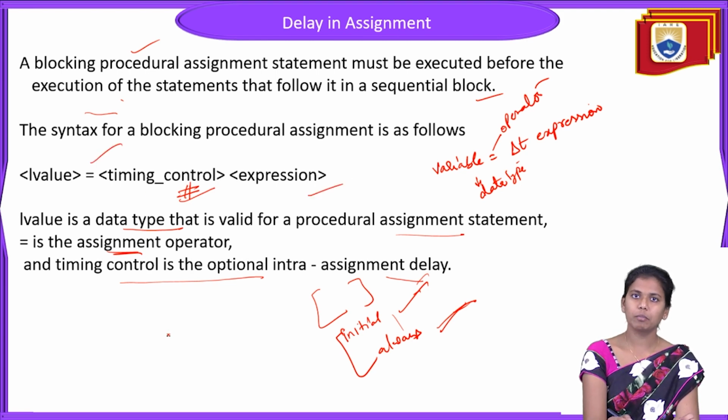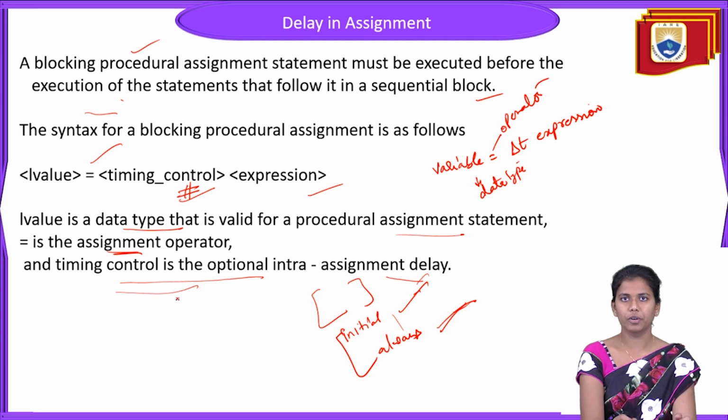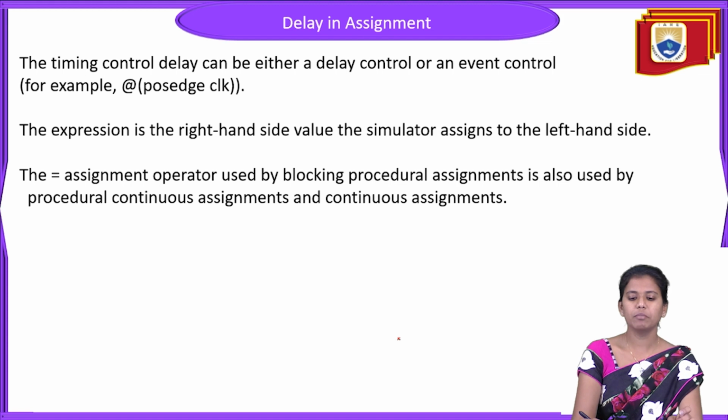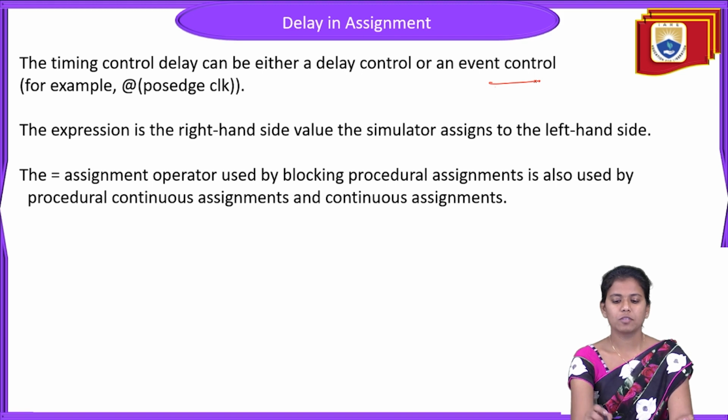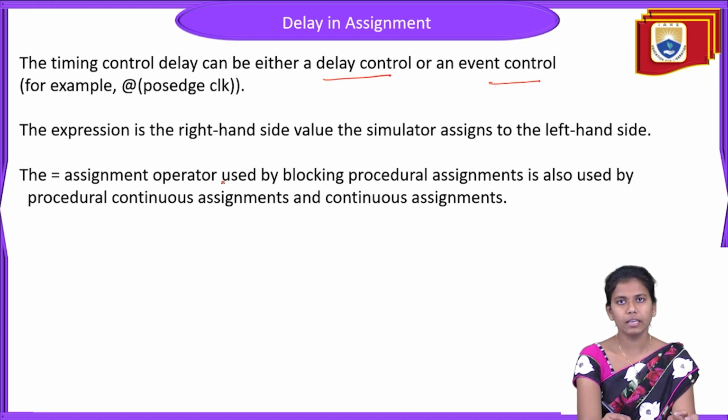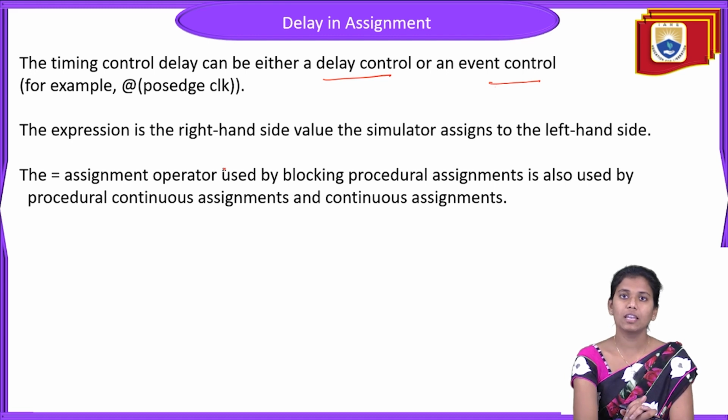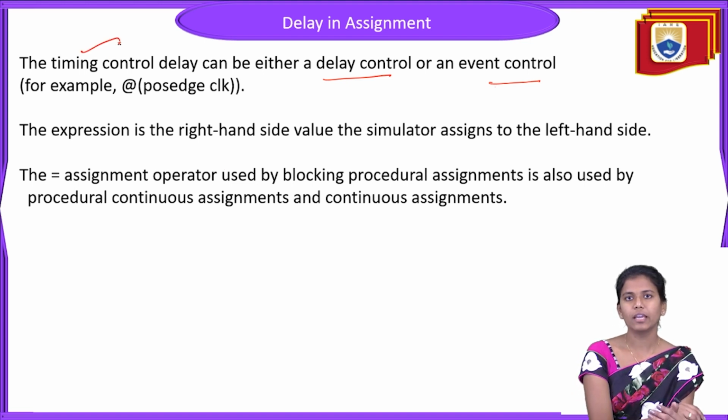Equals to is an assignment operator. So whenever you are writing the syntax for the statements that you are considering, this is to be followed. The timing control delay can be either a delay control or an event control. Already regarding the delays, in the last module we had discussed what sort of delays there are and how many kinds of delays there are: event delays, timing delays, and so on. So here the timing control delay could be either delay control or event control.